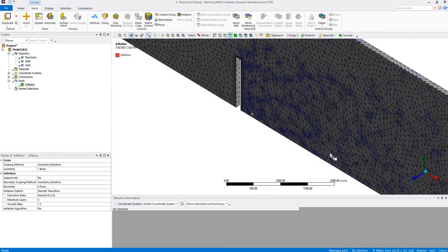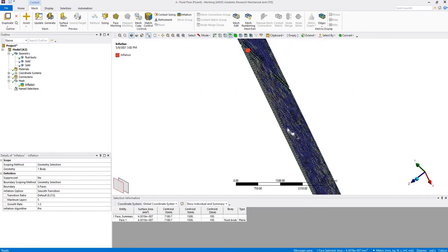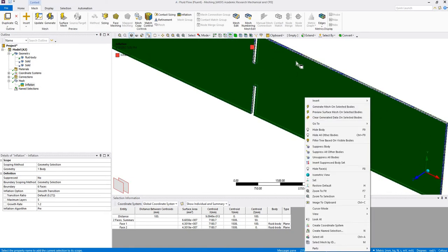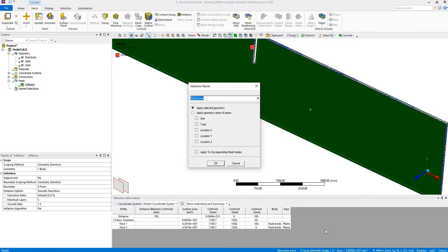And let's say these two are side walls. I'm specifying these two differently because I just don't want to have the no slip condition affecting the flow. So I'm gonna just apply a zero shear condition over there. Okay, so let's say side walls.